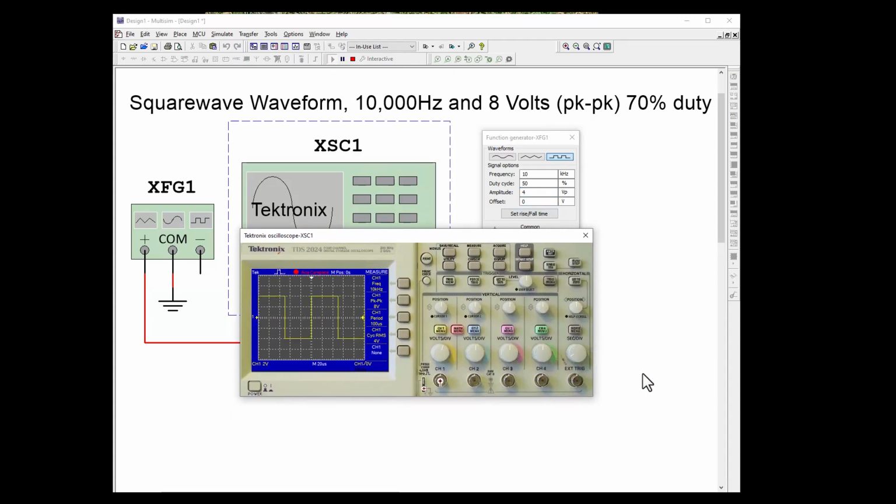And we can move this over. And we still have our settings here. So we have the period 100 microseconds, frequency 10K, and I'll go ahead and get rid of the cycle RMS, and let's go time high, positive width, and let's go time low, negative, or minimum. Whoops, not minimum, it's going to be negative width. Alrighty, and we could calculate this to find the duty cycle.